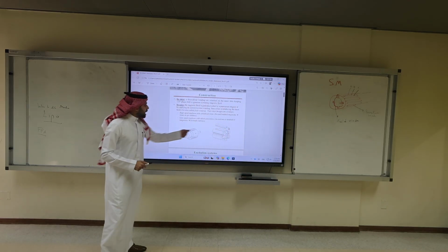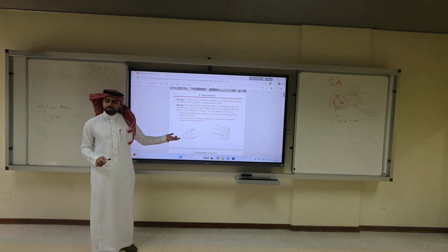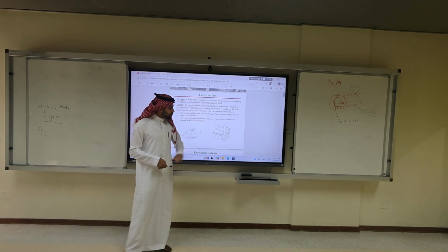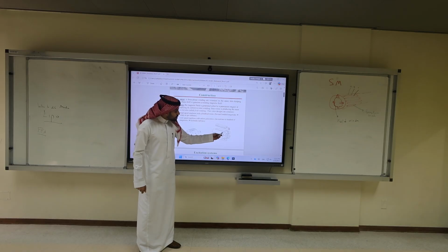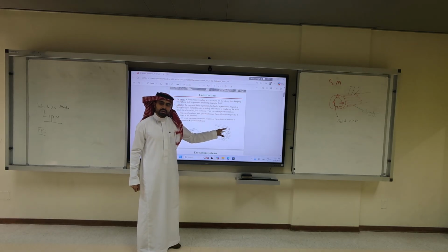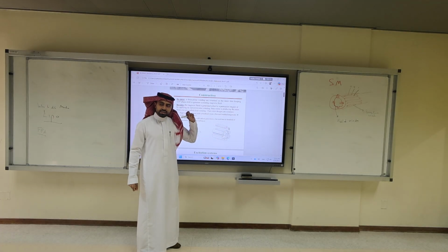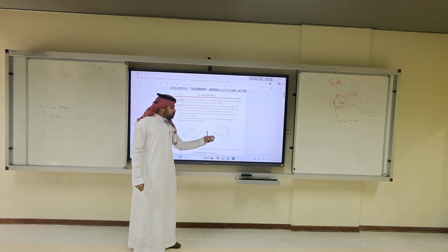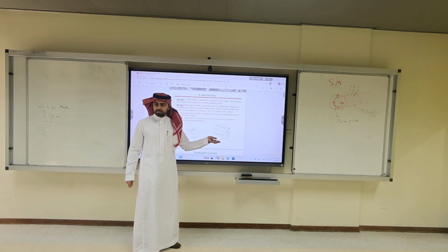So we have two types of synchronous machine rotor. We have the wound, and we have the salient pole. Now this is north and south. It doesn't mean there is an actual magnet here. It can be a steel that is magnetized. Sometimes we put permanent magnets. That's the easiest solution.